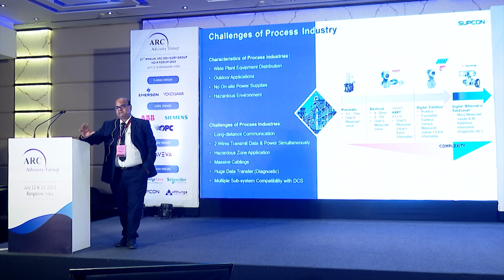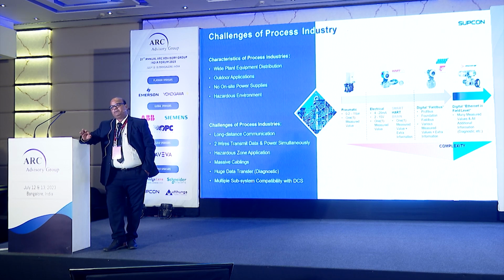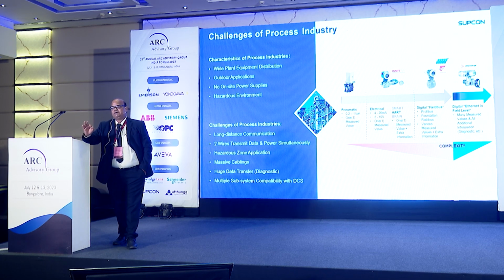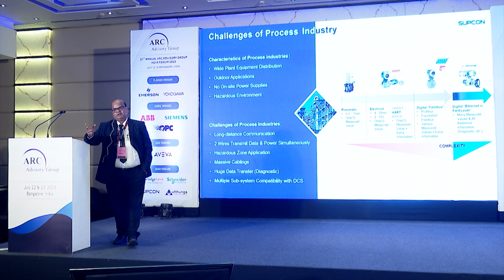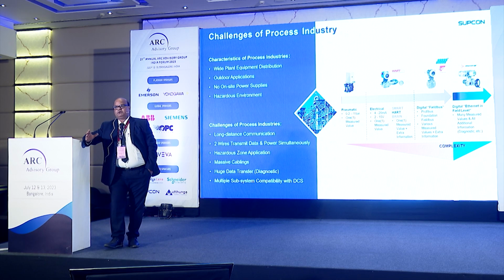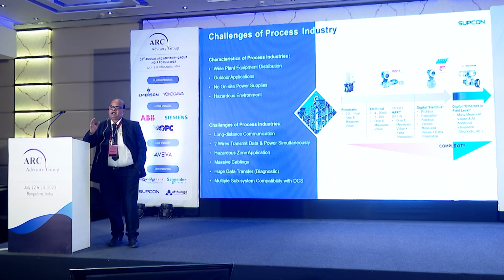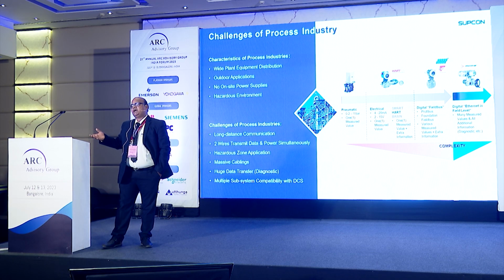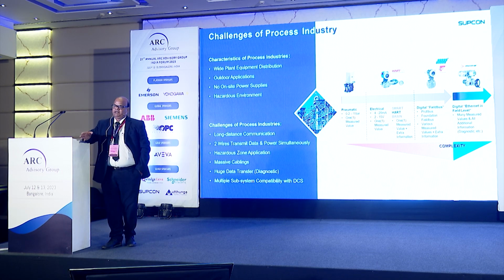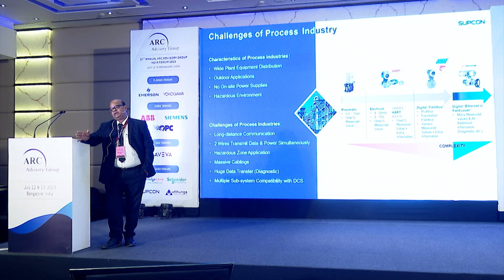Still we don't have the data, because every plant will work differently. Why? Because every city's waste characterization is different. If urbanization is more, waste quality will be good. If it is villages or tier 2, tier 3 cities, organic waste will be more. So we need to control the parameters, get the data, analyze it, and apply it in the next engineering stage, because I look after the control and instrumentation engineering as well as the operation and maintenance of the plant.